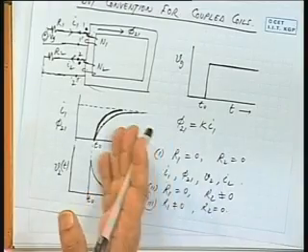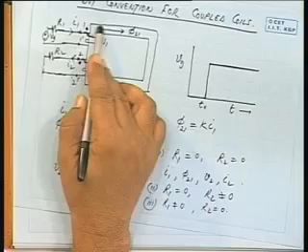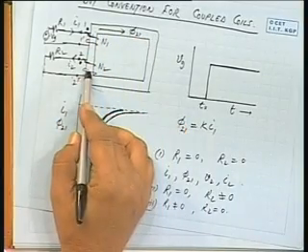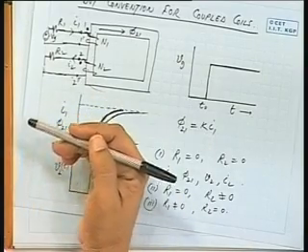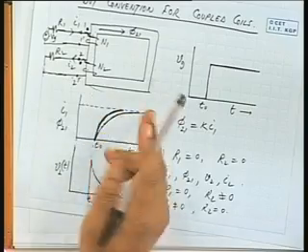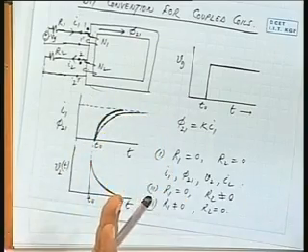So, if it is L di by dt, which is constant, that means the current will be constantly increasing. It is proportional to the integral of V dt. So you will get a current that is continuously increasing, and that will cause a secondary current also, in the reverse direction, that will also be constantly increasing. So, both primary and secondary currents will be increasing continuously.